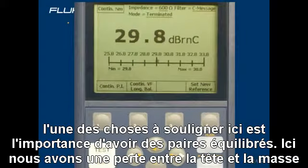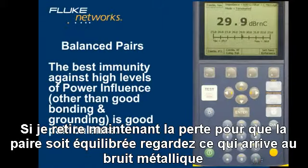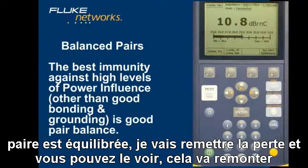One of the things I want to stress in this video was the importance of having good balanced pairs. I already told you that I had a fault between tip and ground. I want to show you what happens when I take that fault off. If I remove it now, such that the pair is now balanced, look what happens to the metallic noise. It drops from 29 or 30 all the way down to 10. So you can see I have taken care of a noise problem by just making sure that the pair is balanced.